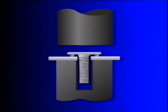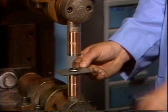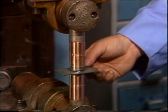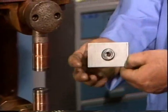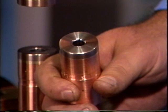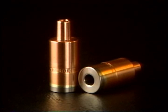The electrodes for projection welding must be large enough to cover the entire fastener to be welded. Therefore, these electrodes are usually flat with large diameters. The more bearing surface that can be obtained, the greater the electrode life. In longer production schedules, a 1/4 inch thick pad of RWMA Class 12 copper alloy brazed to the surface of a regular electrode is recommended. We offer this feature on our Ohio insulated electrodes, designed for Ohio through-hole screws or pins.